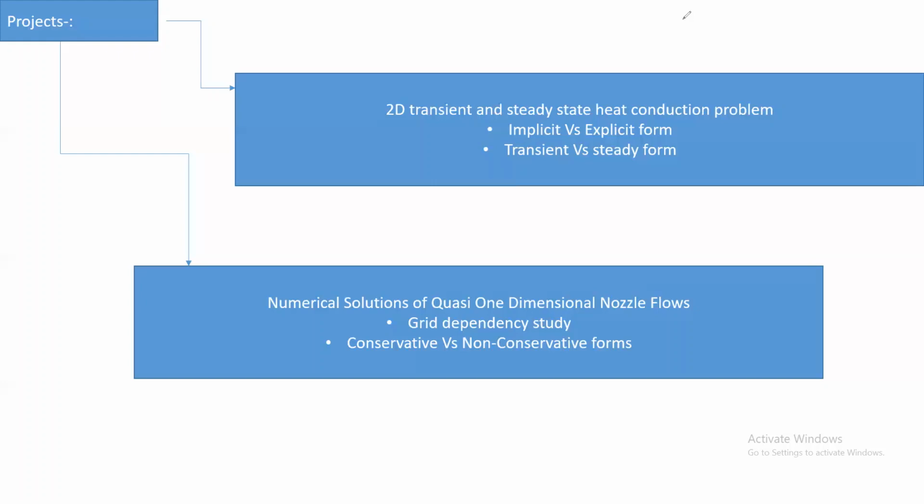When we study the airfoil, we can see the pressure on the lower surface is higher than on the upper surface. That is why the aircraft gets lift. Pressure on the lower surface is more and pressure on the upper surface is less. That is why it gets lift. And the velocity of air on the upper surface is more than the lower surface, right?